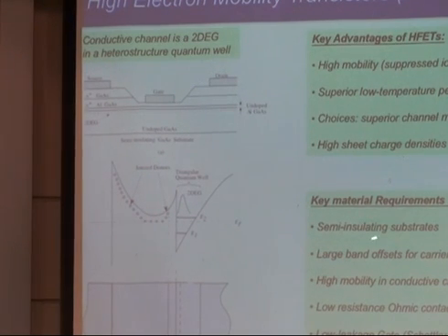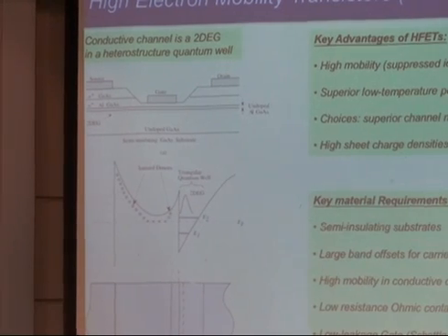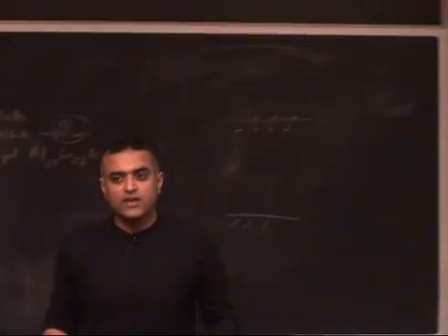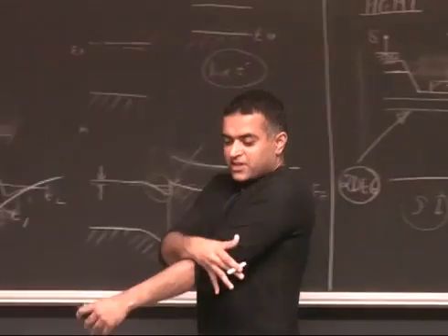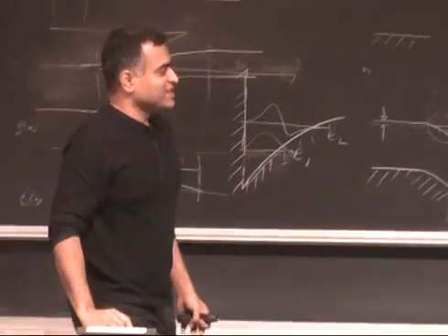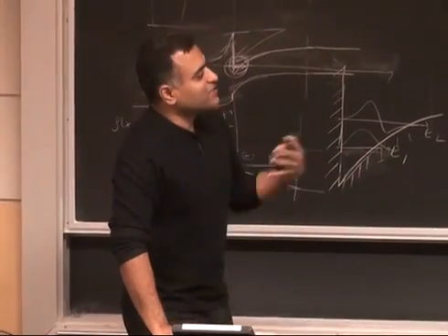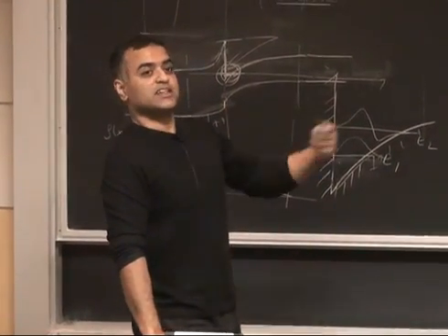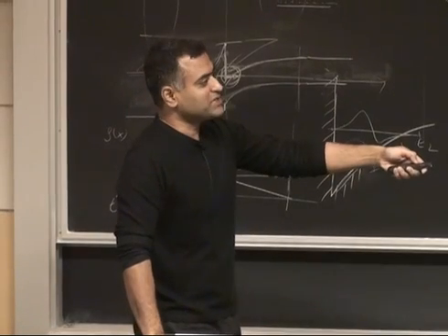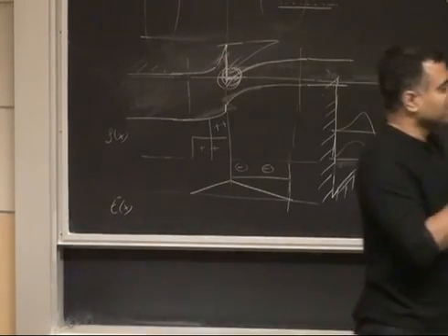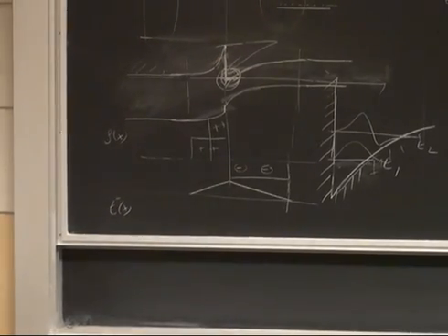It is the fact that you must have a semi-insulating substrate. Without that, you don't get off the first base. There's nothing to do if you don't have a semi-insulating substrate. And this is something that a large fraction of the community doesn't quite realize, that this is the key. Semi-insulating substrate, and it is more important to make it insulating than conducting.